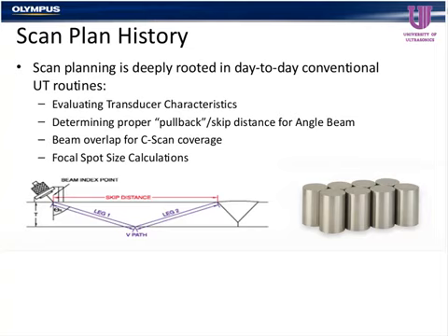But really, scan plan comes from what we do on a day-to-day basis in any ultrasonic examination. Anything that has to deal with how you implement a UT test, down to transducer selection, down to evaluating sensitivity or resolution characteristics.